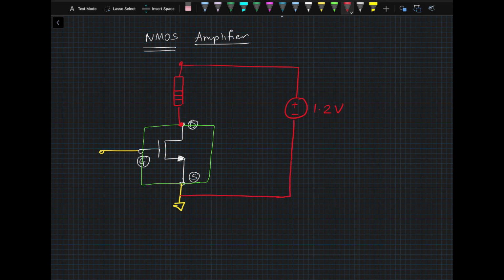Okay, so now I'm also going to connect the input here. This is our AC input, VAC, which we show with this tilde sign, like a sine wave. Then we have a DC input, which we show as plus minus like this, and this part will be coming from your signal generator, the one on the left side here. We connect this with a wire. All these different lines are wires, and I think that's pretty clear.